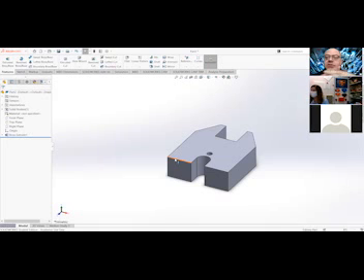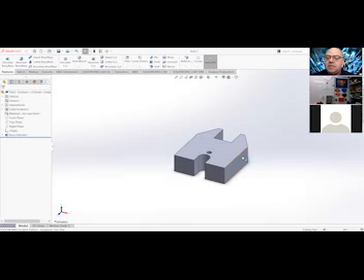We talked about when I showed you the fillet, the sketch fillet tool, there's a chamfer that puts a beveled edge. When we work with machine parts, especially metal, you never want a 90-degree corner where someone's hand is going to be because it will cut them. And so what we want to do is soften these edges around the perimeter of this base. We do that with a pretty even 1/16 of an inch at a 45-degree angle on there.